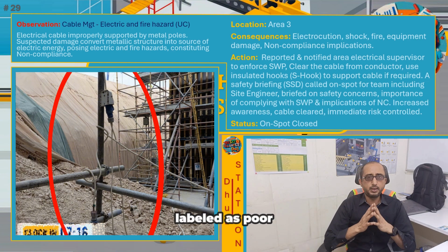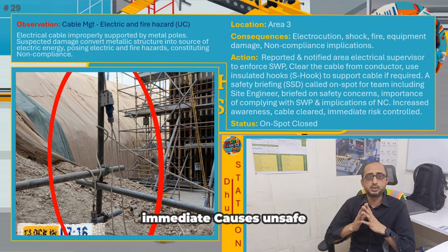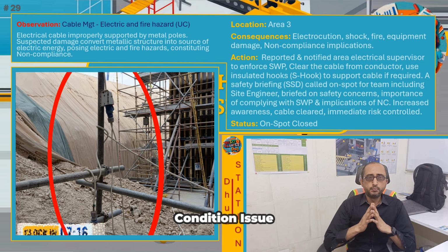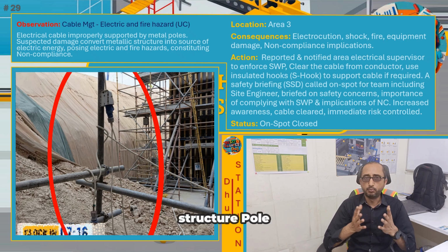This observation is labeled as poor cable management. Hazards include electric and fire. Immediate cause is unsafe condition. Issue: our safety team noticed our electrical team supported their electric cable directly with the metallic structure poles.